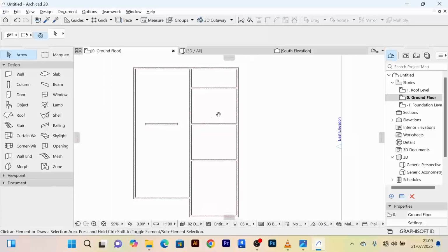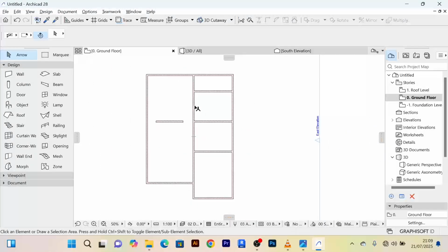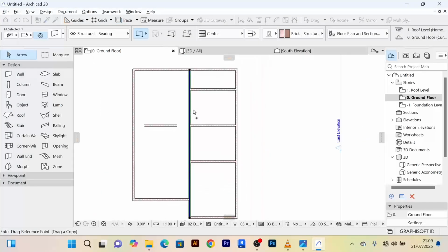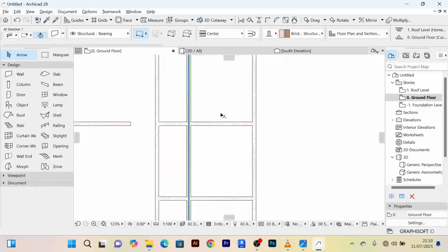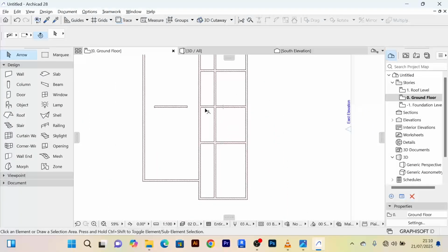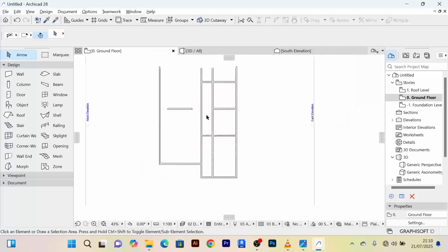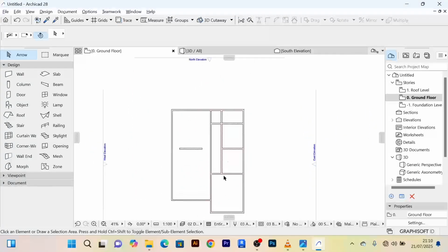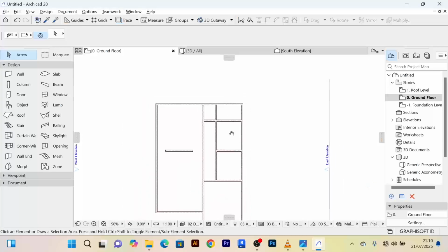First of all, I am going to offset this wall, Control Shift D. I'll drag this wall a little bit here by 1.7. That will give us 1.5. Then of course these parts I'll delete them off. Control delete, just like that. Control delete, just like that.